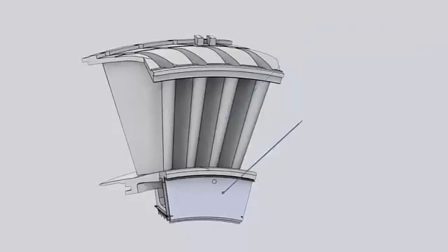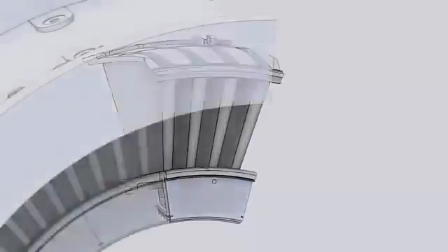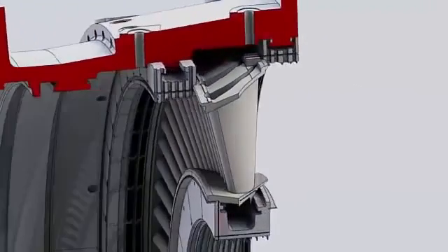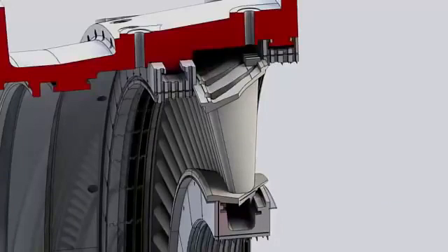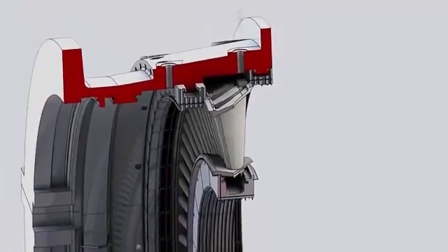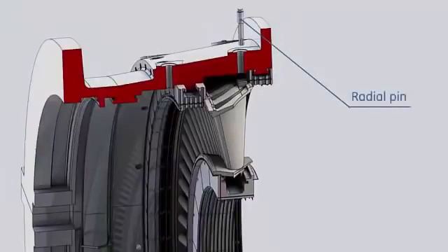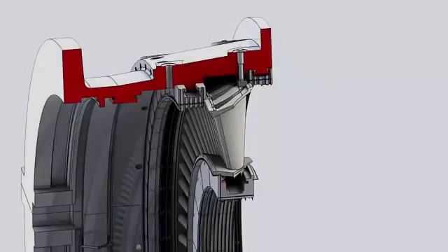A diaphragm segment is also attached to the inner sidewall of the nozzle. The third stage nozzles are not air-cooled. These segments are installed to the stator in the same manner as the second stage nozzle. The third stage nozzle is supported by the second and third stage shrouds. The nozzle segments are held on the circumferential position by radial pins from the turbine shell into axial slots on